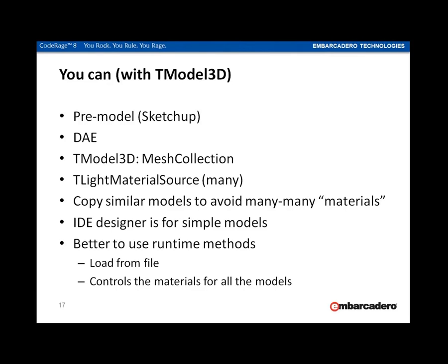The most important property is the TMesh collection. After loading, both in design time and runtime, don't forget to change the scale property, especially if you have an empty TDummy 3D component with 0 scale values initially. Then you can have many materials. Don't worry, we can reduce their number later.